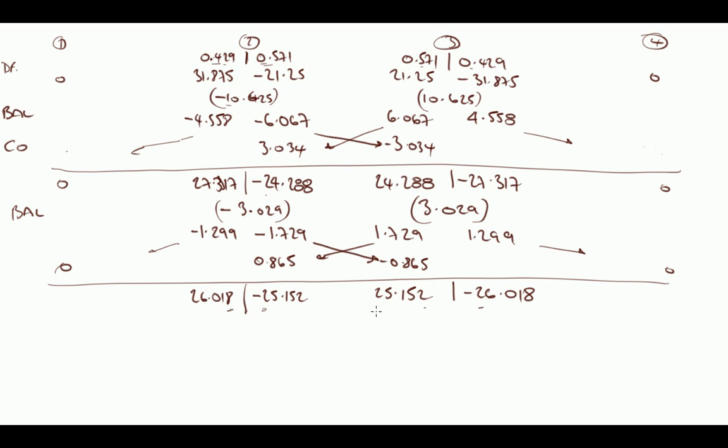Okay, so I need to keep going until my moment has been distributed throughout the structure such that I have an equilibrium state. Okay, and you can sensibly stop when you get to within 3 significant figures. So we are getting close to, but not quite there yet.